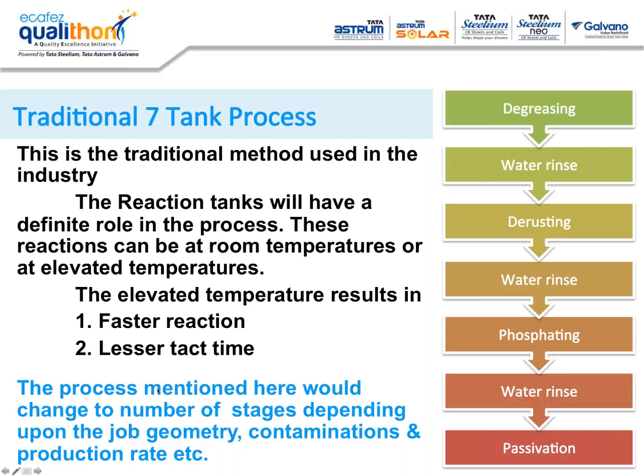The reaction tanks will have a definite role in the process. These reactions can be at room temperature or at elevated temperature. Now that is a regular question asked by people: if I can do the treatment at room temperature, why should I do it at an elevated temperature? The first reason is, when you elevate the temperature, the chemical reactions are better and faster. Number two is you can generate higher volumes due to lesser takt times available.